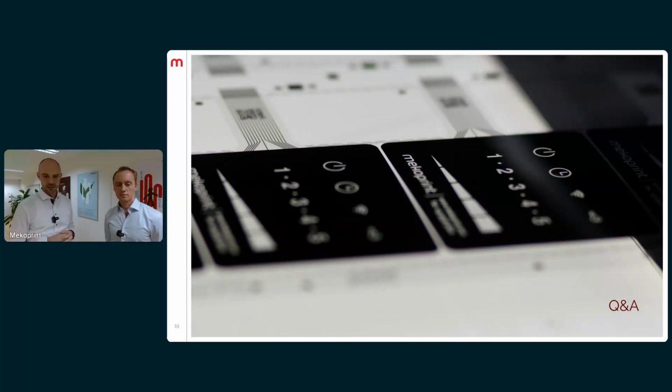And I think maybe we answered it a little bit before, but again, for example, in the applications with capacitive touch, we see a tendency to use different types of SIF connectors with different pitch sizes, but that seems to be the go-to for capacitive touch, where the SIF connectors are directly on the PCBA. If we again look into the healthcare segment, we see a wide variety of different connection methods. Some customers are using spring-loaded connectors, some are using snap button connectors, some are using SIF connectors as well.